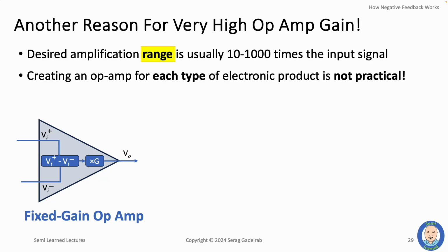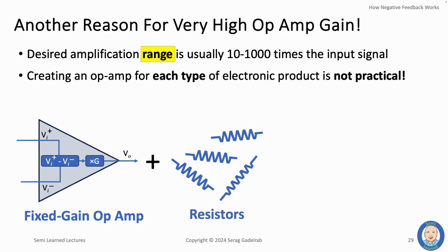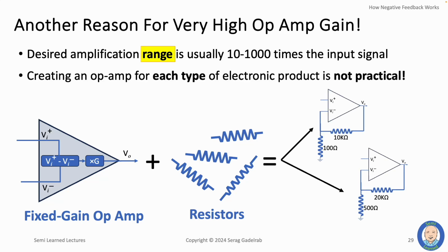Such adjustments should be done using cheap components like resistors, which, when attached to the external terminal of the op-amp, would produce an amplifier whose gain is proportional to the value of these resistors. If the gain of the amplifier is proportional only to the value of the resistors, end users will have full control of the resulting amplifier gain. And we have just seen exactly that concept through the amplification equation of the non-inverting amplifier. And here are two examples of this concept.